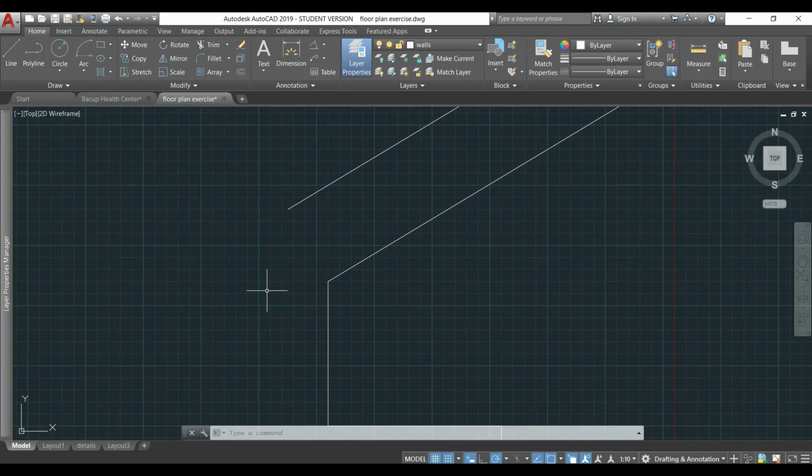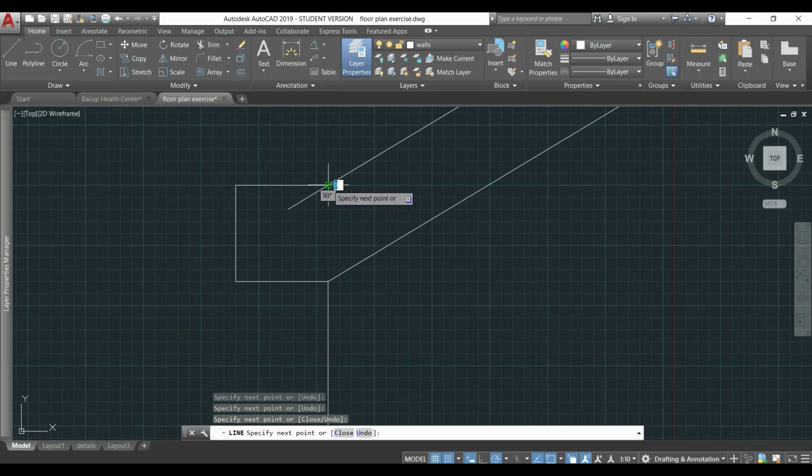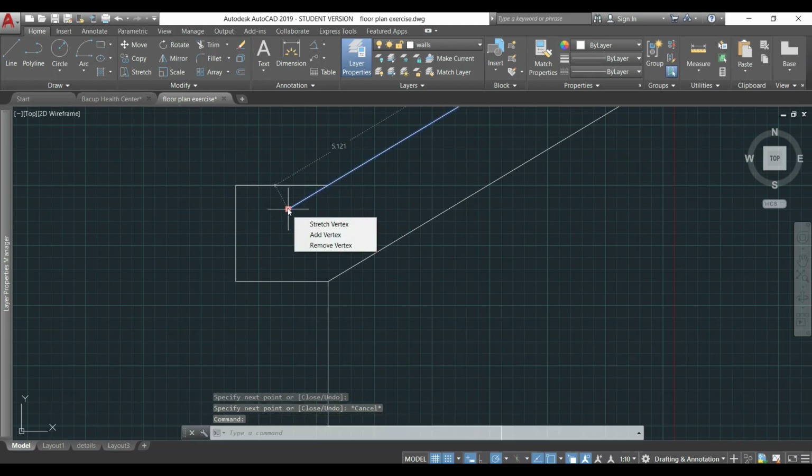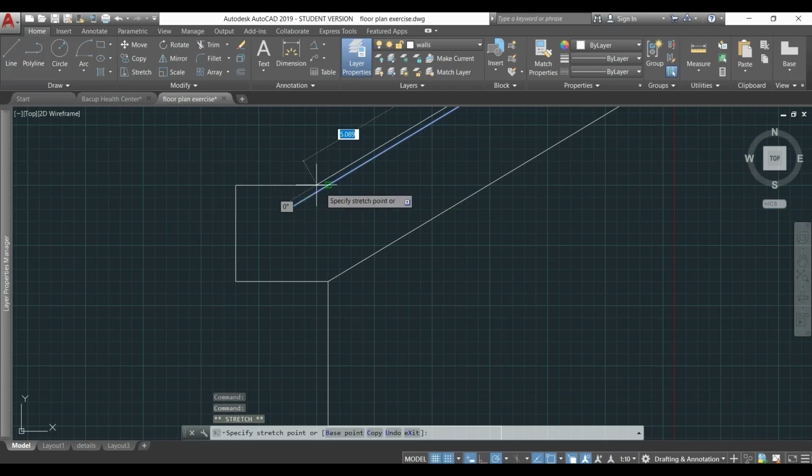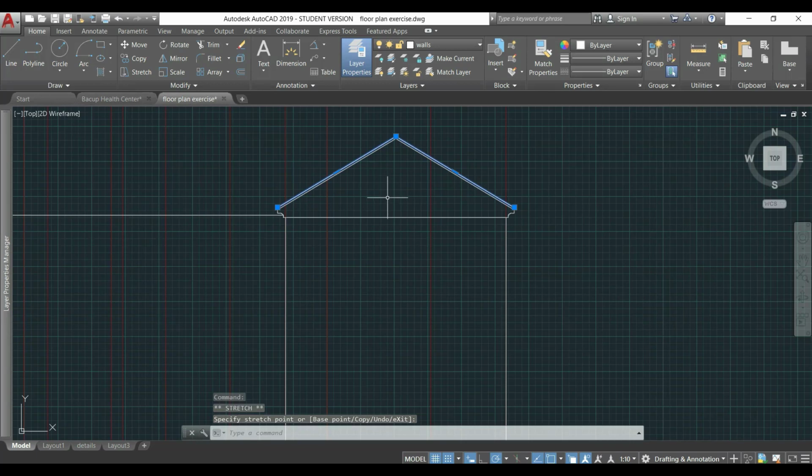On the left side, I could use Mirror to copy the lines that I didn't draw, or I can still draw them quickly. As I'm using the grid and snap modes, I can draw them quite simply. Then the diagonal line. Another option is to select it, click on the endpoint, and extend it until this intersection. Now the elevation of this roof is finished. Part number 2.